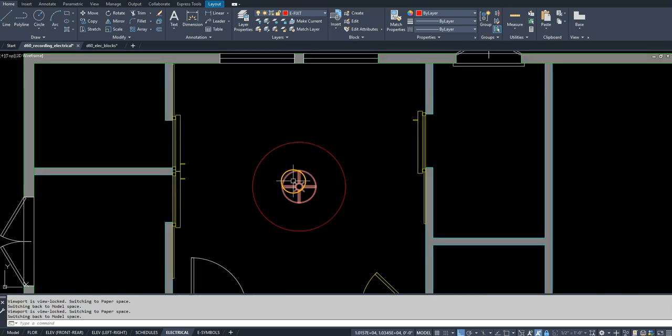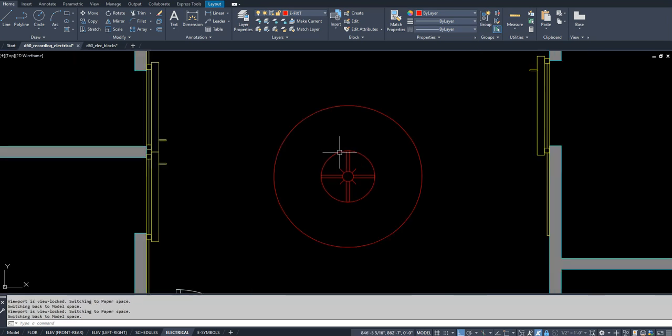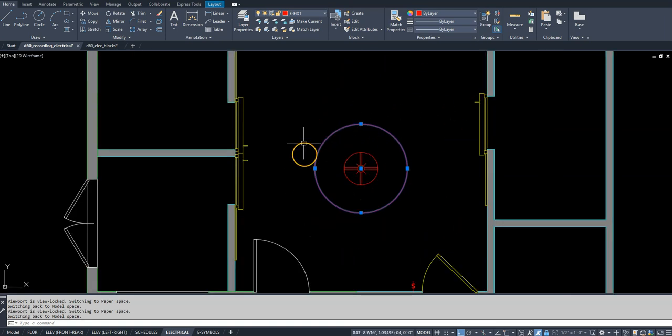All of the other symbols will stay the same size. So the fan, if you're going to use fans in your house, I recommend you use the same size fan throughout the house if you're using multiple fans. The best and easiest way to scale this so that it fits a 5-foot diameter fan. Again, you can use a 4-foot diameter fan, you can use a 6-foot diameter fan. Most common are a 4-foot and a 5-foot. For this particular room, since the room is quite large, I'm going to use a 5-foot fan.